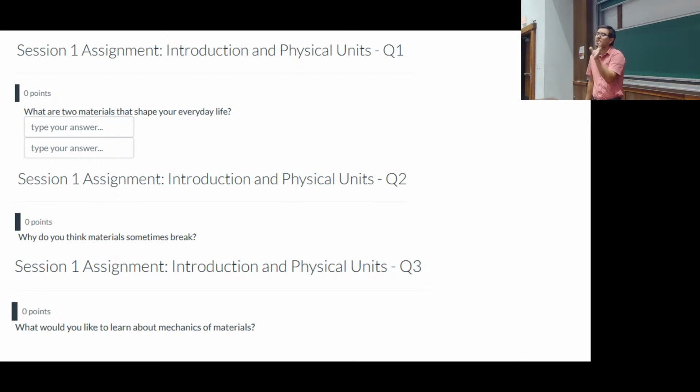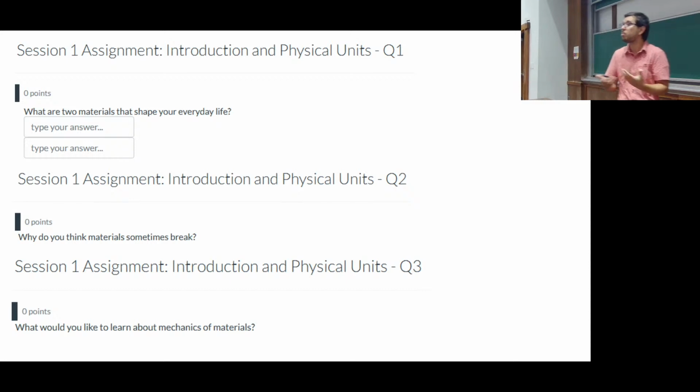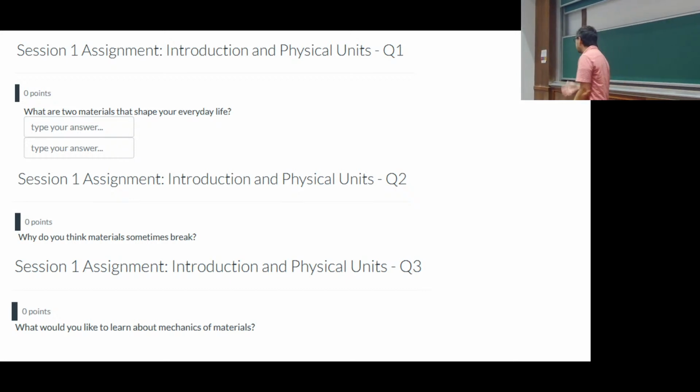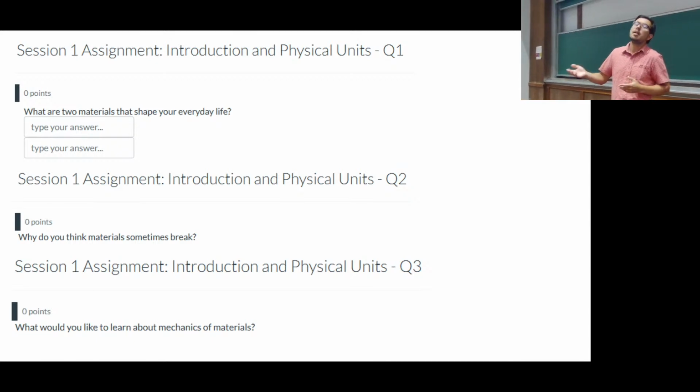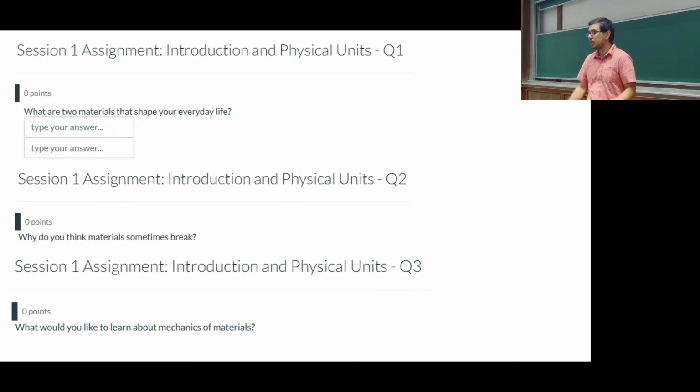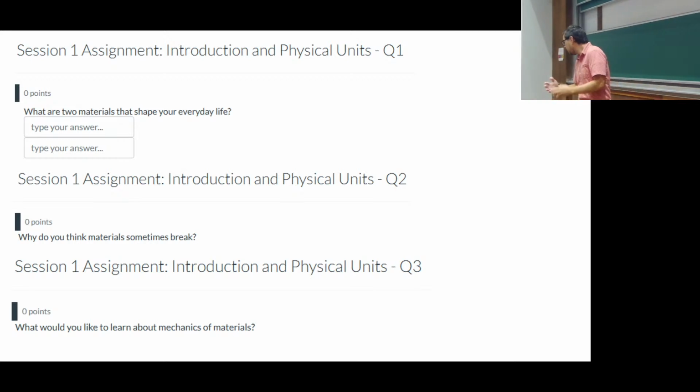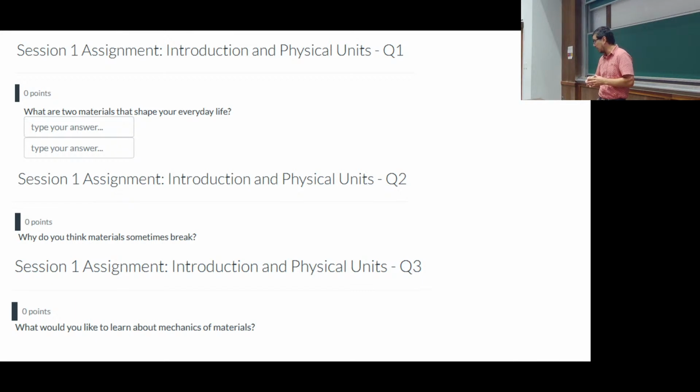So often when we say mechanical properties, we're not being very specific. Is it the structure that we're talking about breaking, or is it the material that we're talking about breaking? If the material is the thing we're interested in studying, then it's kind of this intrinsic property. Of course, it's related to processing, crystallinity, cross-linking, like we were talking about. It's related to a bunch of different things: composition, heat treatment, whatever stress has been induced in it. Even hardening. We'll talk about a lot of these things in the class.